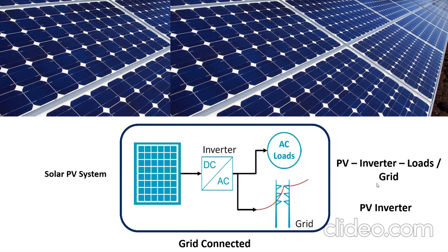In conventional systems, in microgrids or in conventional grid connected systems, these types of inverters can be classified as PV inverters. They are classified as PV inverters because their primary function just interlinks your DC power from the solar panels into your grid, or supplies your associated loads that are local to your generating station.